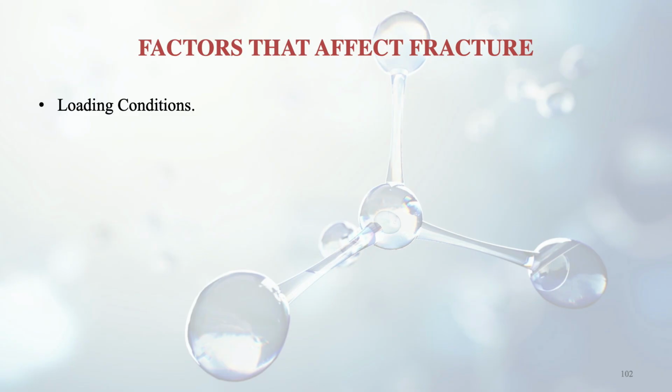Now after discussing the mechanism of shear and the cleavage type of fracture, we move on to the factors that will affect the fracture. Earlier we have also seen this in the case of the ductile to brittle transition. Here also there are certain factors. What are they? Similar to that: loading conditions, the temperature, and the stress and its concentration.